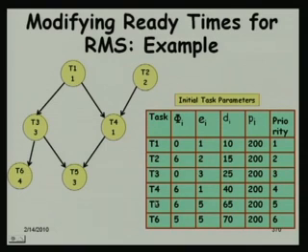Since it is a modified RMA, we don't consider the deadline as a criterion for allocating. No, no. See, the priorities in a rate monotonic algorithm are given based on the frequency or the period. But what we are saying is that here they should all have got the same priority, but we are trying to give them different levels of priority because we want the predecessor to complete before the successor can start.